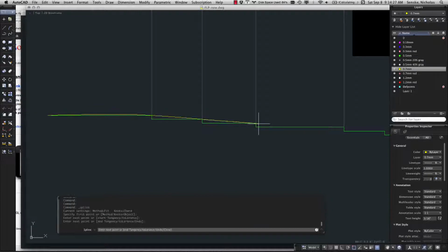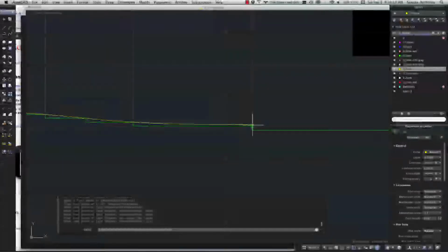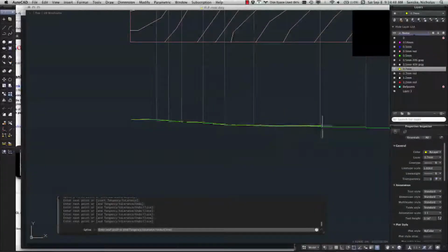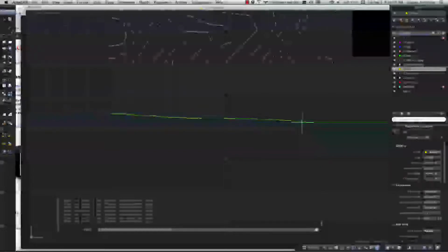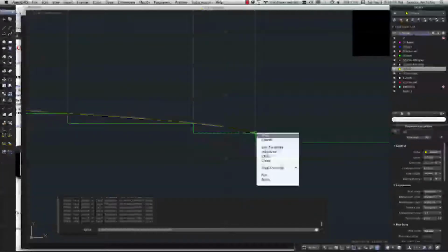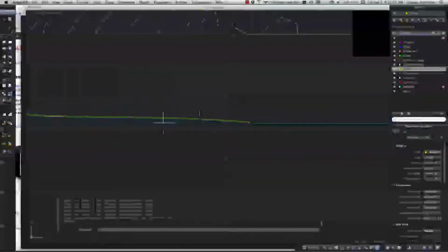spline it together. So you're just going to take the ends of this. I'm missing a construction line there. Fix that. And that would actually stop the spline when you get to the water. And I'm clicking and I'm panning with the middle mouse as I'm going. Yeah, so there's the end of the water there. I might trim that off, but okay. So that's how you get a smooth line.